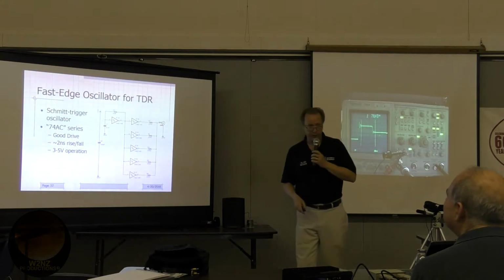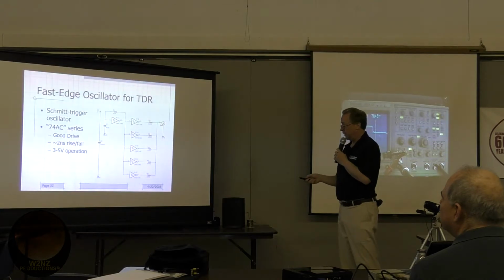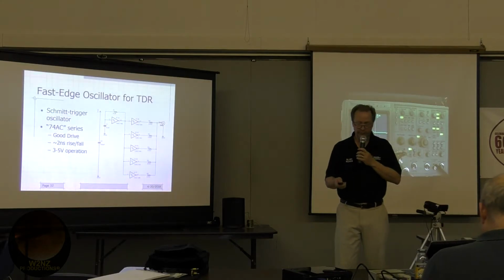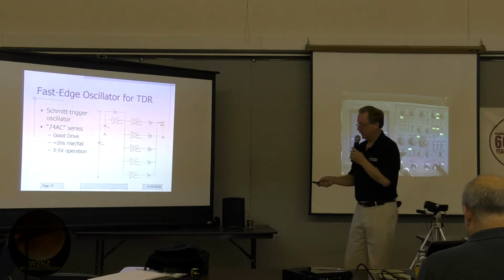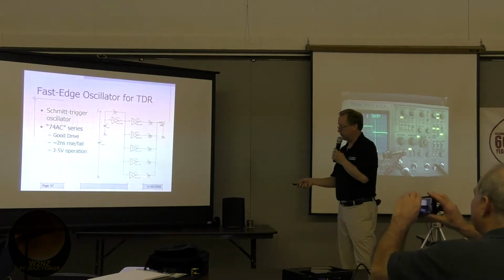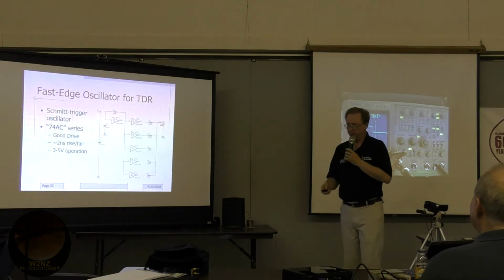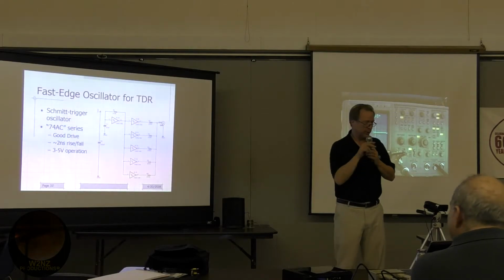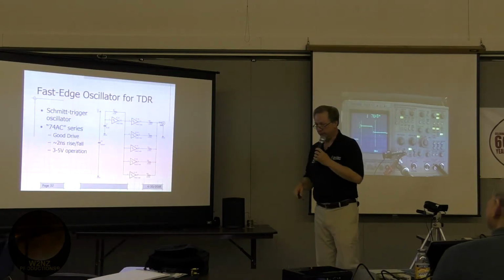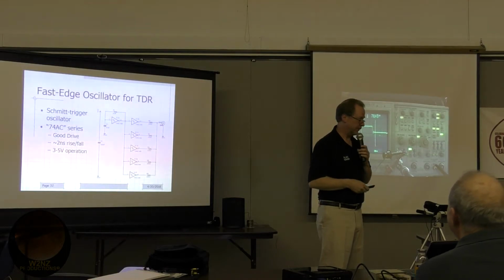This is the oscillator that I'm using. Okay, and it's really just, again, a 74AC14. The advanced CMOS, I picked that because it can drive relatively low impedances, and it's really fast. So it's just a simple circuit, a simple little relaxation oscillator, followed by a couple of buffers, all in parallel. All these 220 ohm resistors in parallel give me an approximate 50 ohm output impedance. So it could drive that 50 ohm coax. And this will run from about 3 to 5 volts. But anything that creates a nice fast sharp edge, a nice fast logic family, will work fine.